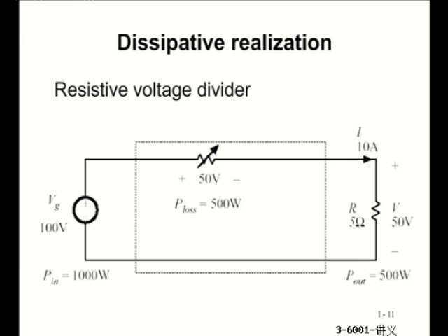But obviously, as an engineering student at college level, you would instantly find there is a big disadvantage of this. What is the disadvantage? Power loss. Because this resistor in the power converter is going to be taking 50% of the input power, consumed on this resistor, and only 50% of the input power is transferred to the load. So the efficiency of this solution is only 50%. That's too low.